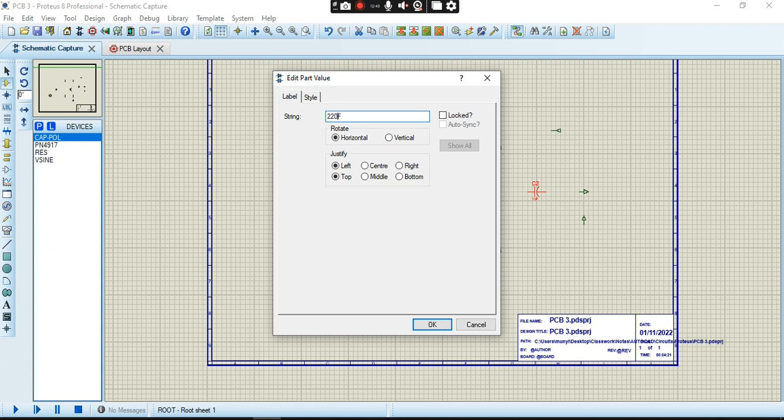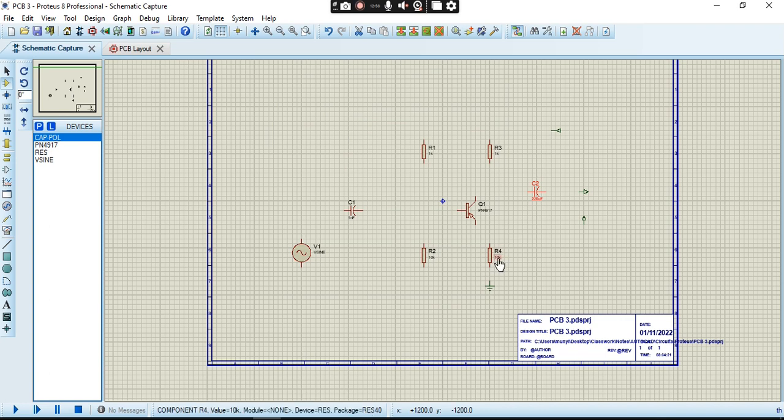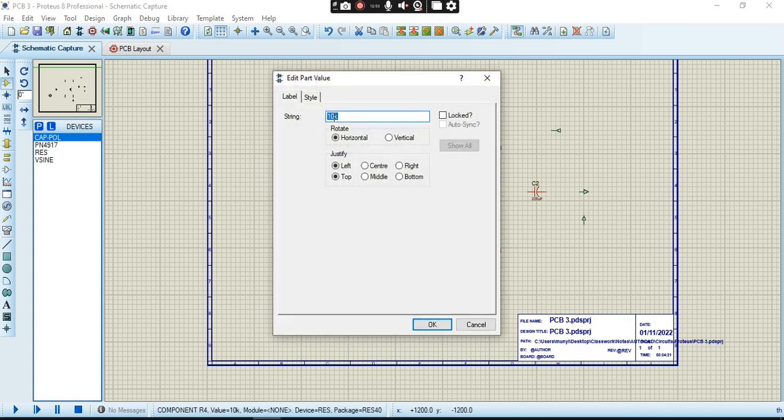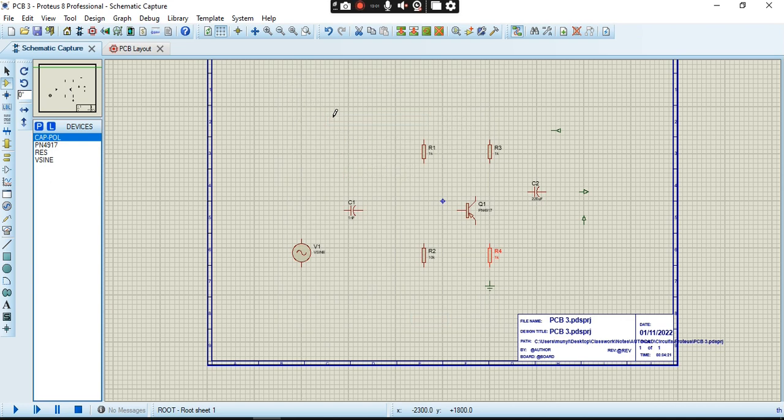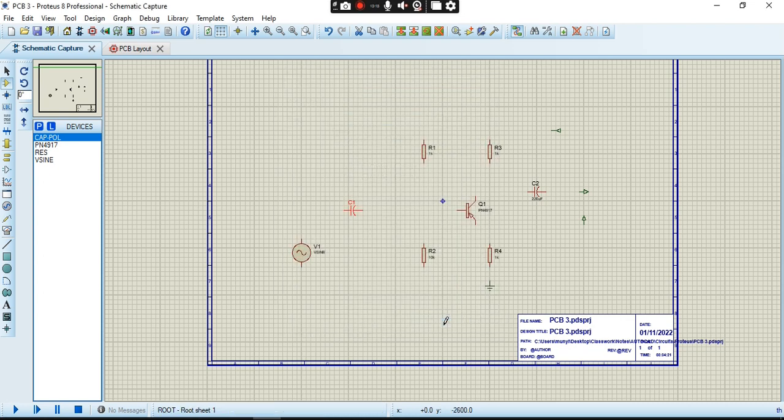and to represent the micro, you use U so that you can get the micro symbol. Okay, so you keep doing it, keep editing the labels as needed. This capacitor does not have a label, this one. So let us see if we can erase that by erasing it. Yeah. So if you delete the name of the label, then it also goes.